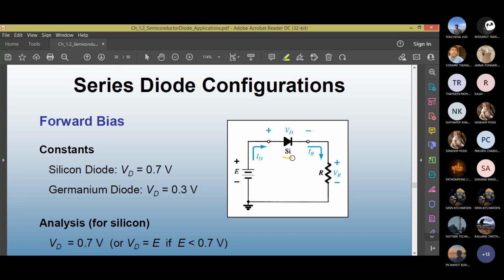This diode is showing silicon, Si, under its picture. So once it turns on, the voltage will be 0.7 volt. If you put a battery voltage of 0.2, it will not turn on. You should have a sufficient amount. Now, if it was germanium, it would say 0.3.